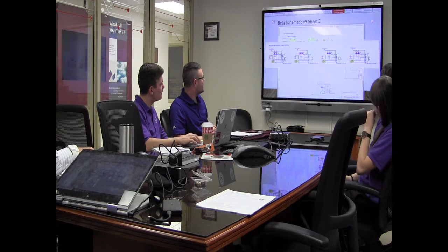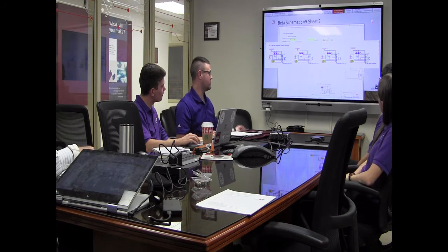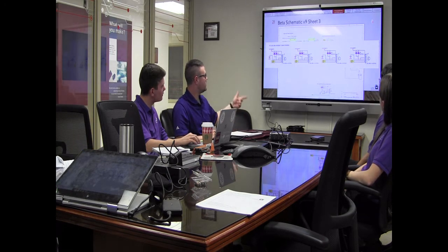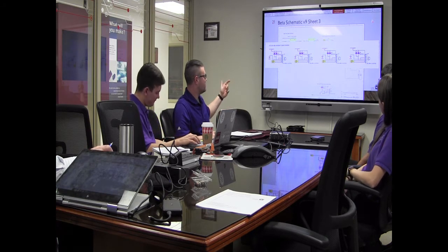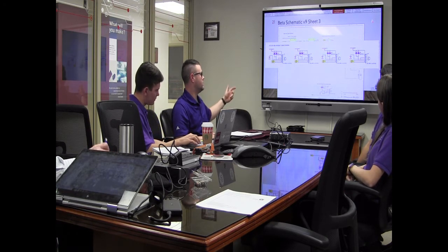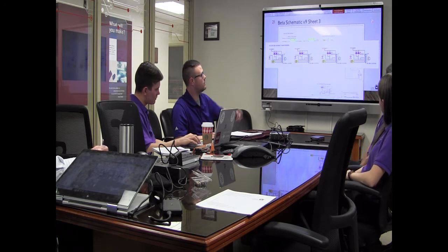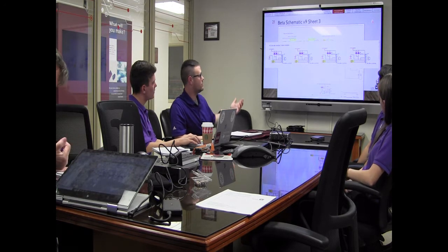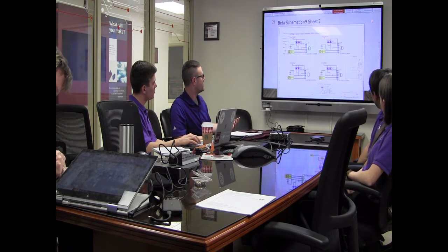So that's that. Here's the 4 low side switch control modules with the different selectable voltages, either 12 volts or 5 volts on pins 1 and 2. 3 and 4 have ground, and then 5 and 6 are low side channel 0, 1, 2, 3, 4, 5, 6, and 7. And all of these are at 60 hertz? All of them are 60 hertz. So that's all those, and then the next one should be the 4 high current control modules.